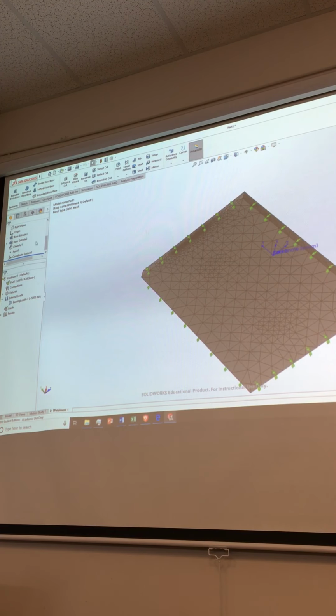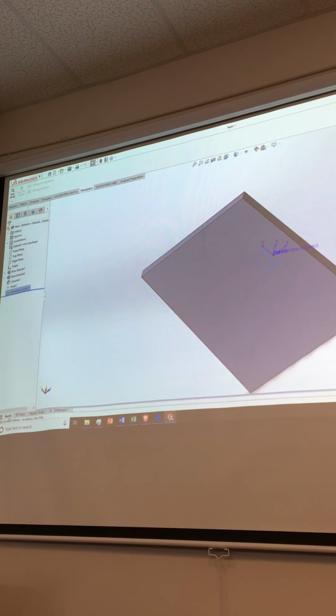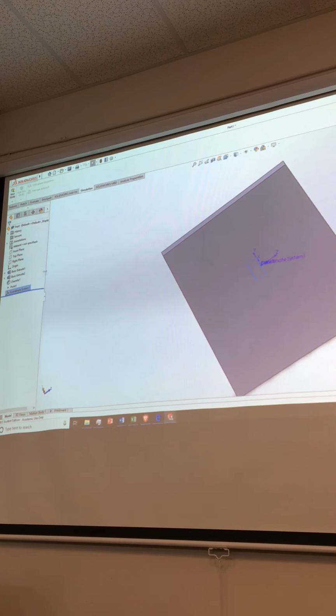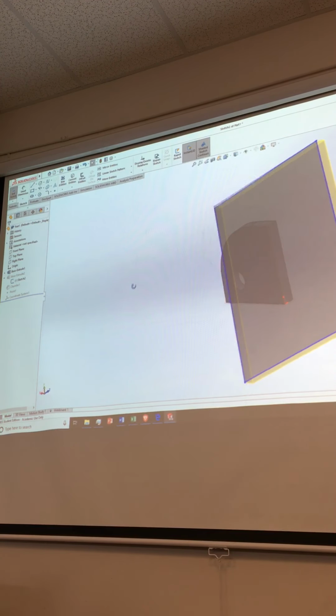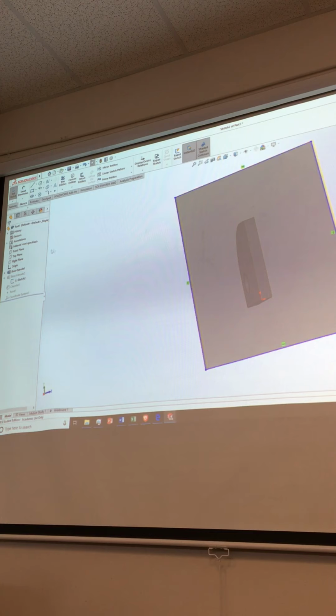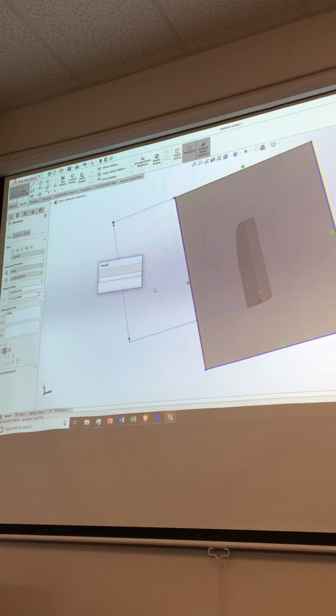Go back to the model here, and we'll get this guy here. There's that sketch. Okay, so edit the sketch here, and let's see, I'm gonna put a dimension on here from the origin to here. Right now I've got 7.5 inches, let's make it like, what, 12 inches?